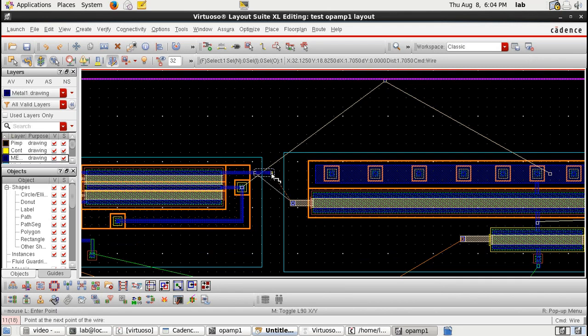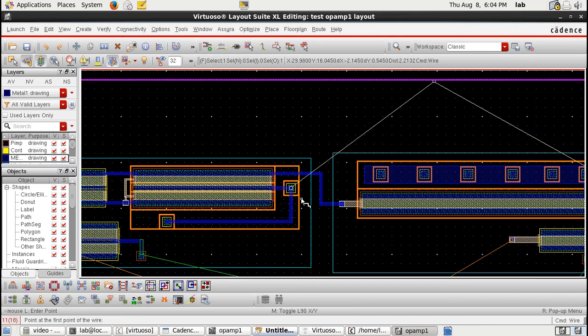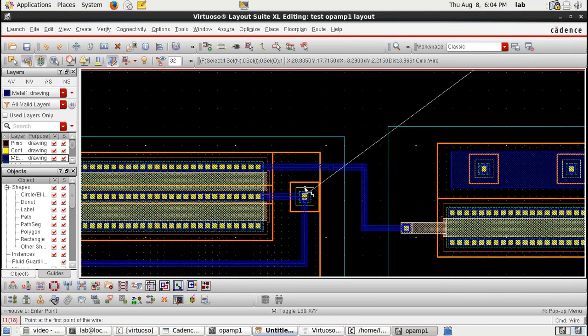We've only used metal 1, but in this design metal 1 alone will not be sufficient because there are some paths that we have to cross over, and taking metal 1 over metal 1 will fail for us catastrophically. So what we really are going to do is place metal 1 to metal 2